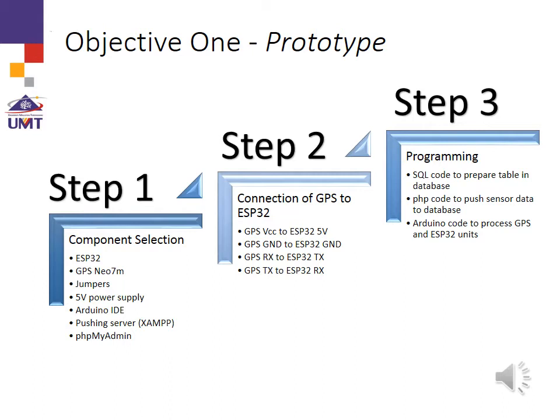The second step is to connect the GPS to the ESP32 module. The GPS VCC pin will be connected to the ESP32 5-volt pin.